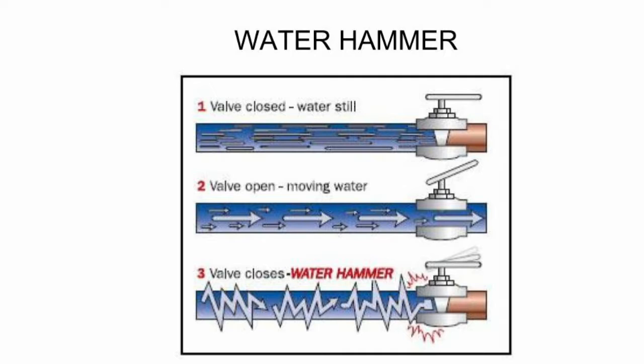The water hammer phenomenon causes a pipe to shake violently when the valve is closed suddenly. A water hammer is when the flow of fluid, usually water, is stopped rapidly, causing a surge or wave within the system.